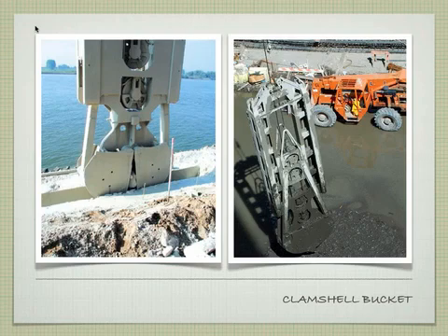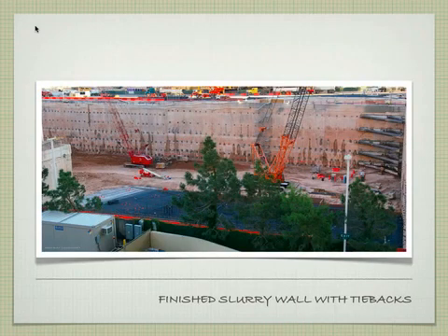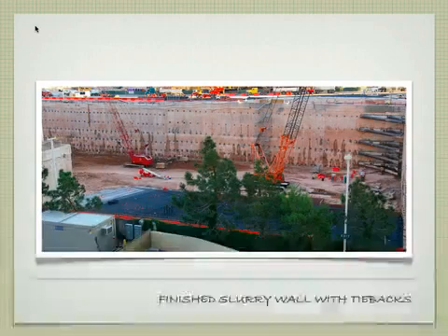You can see the two little poured concrete beams that are helping to guide this big bucket straight down. You can see where if you didn't have those, it would want to twist to one side or the other, and you wouldn't get a straight wall. So you have those two pieces. It comes down, hydraulically scoops, pulls up, and dumps out the remaining material that you just dug. As you go down, you fill with that slurry.